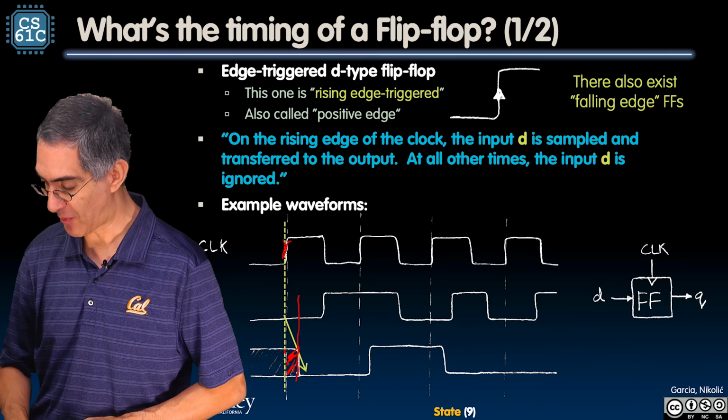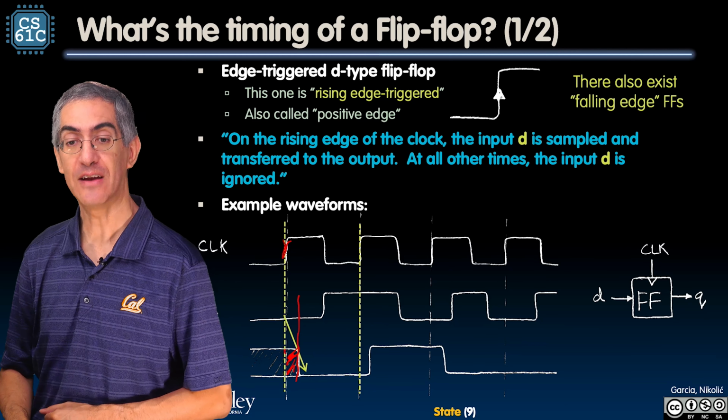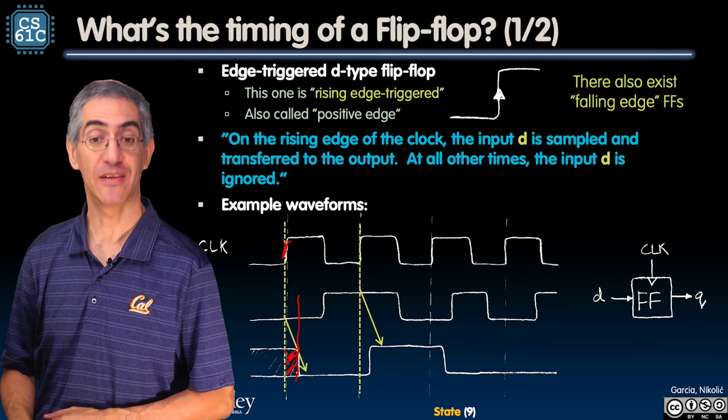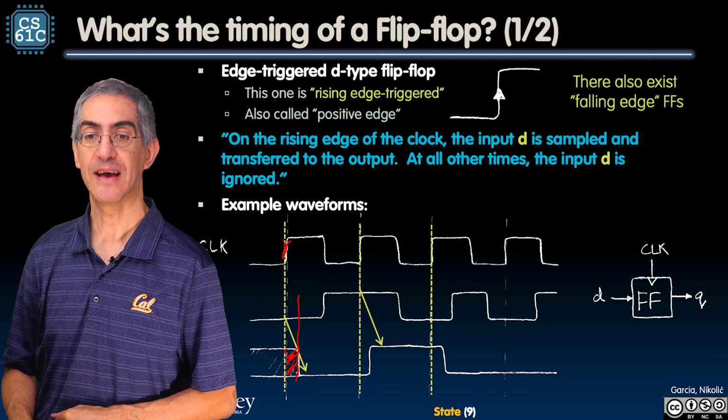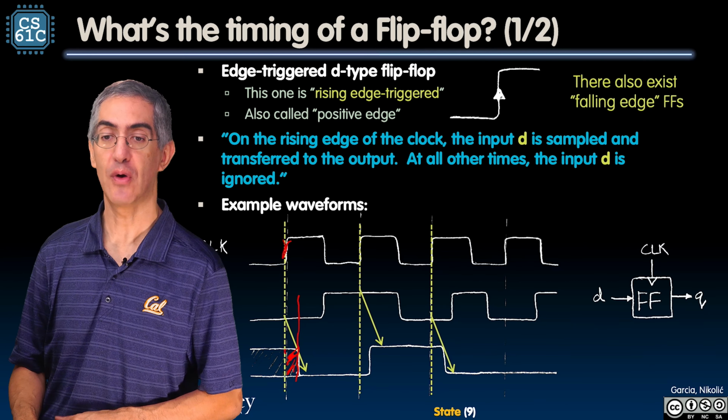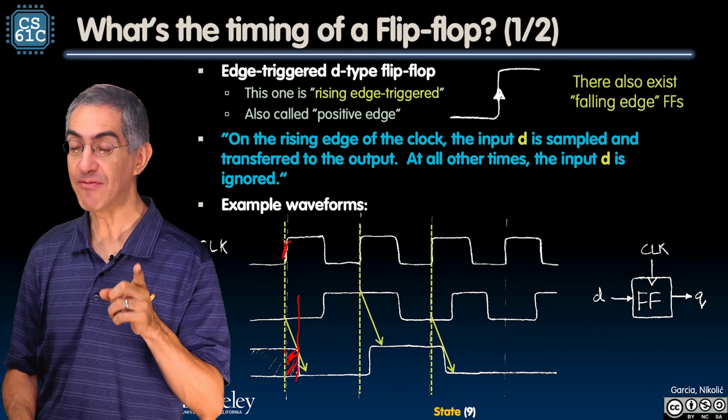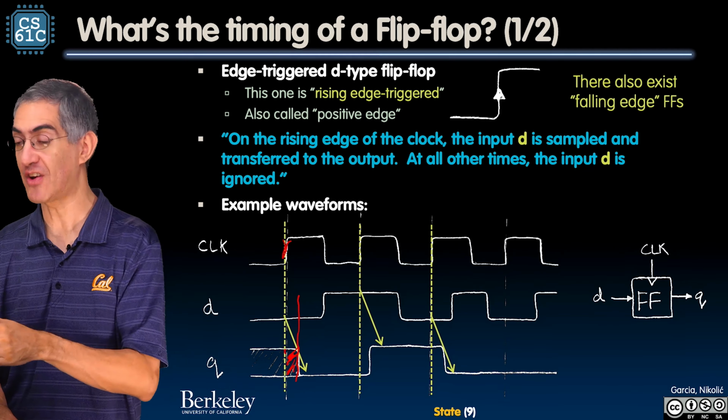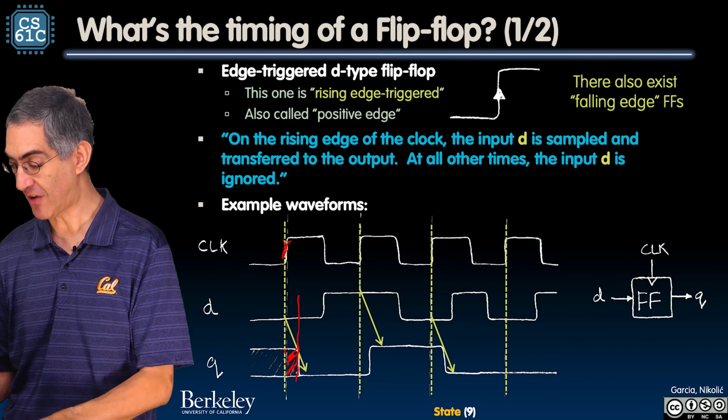And this happens again. If I watch this again, let's keep doing this. There's my rising edge. I sample D. I see the output on Q. Rising edge, sample D, put it on Q, and watch, here's what happens. I even do it if D hadn't changed. Look, D is changing between those two clock edges. Look, D changed in the middle.